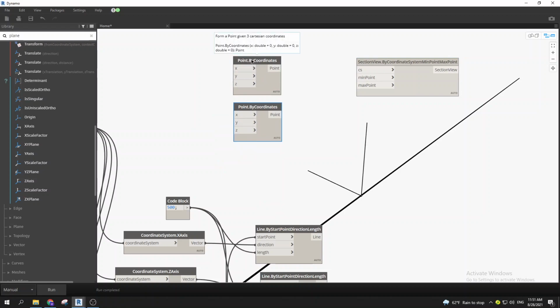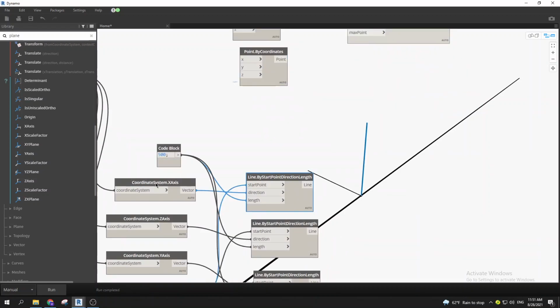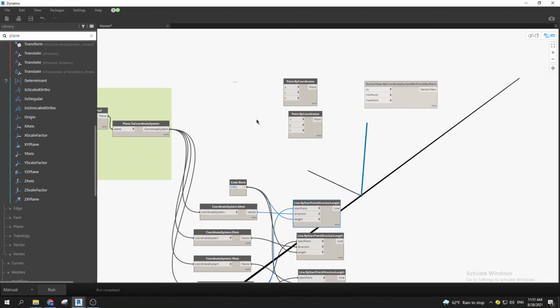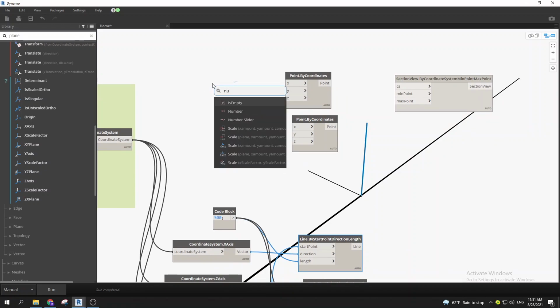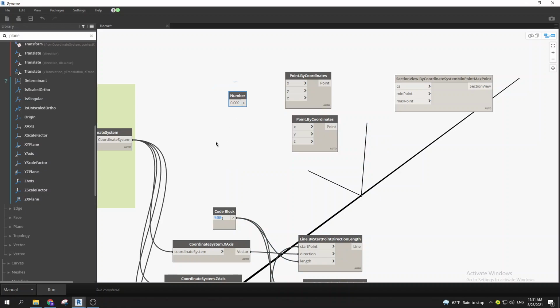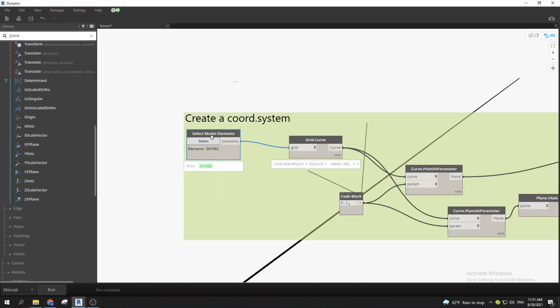What I want to have here is, let's say that we start with x-axis, right? So that is the height. I want to type that for the x, the minimum point, and I'm going to go with number. Actually, what I forgot to do, because we're going to run this through a Dynamo player, we need to right click on the node and say that that is an input.